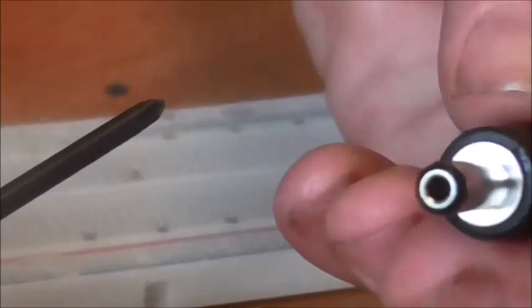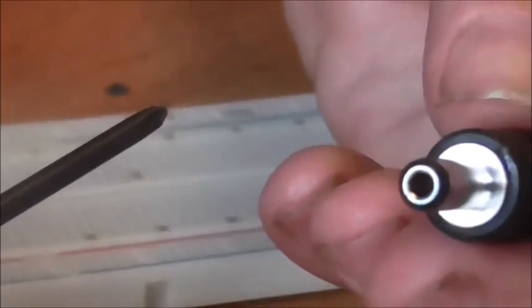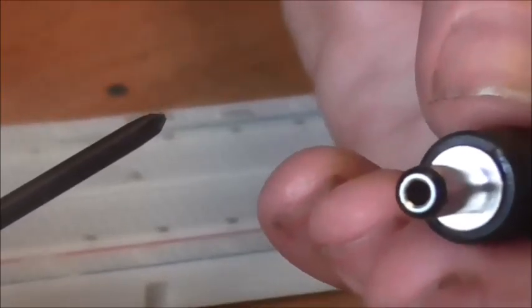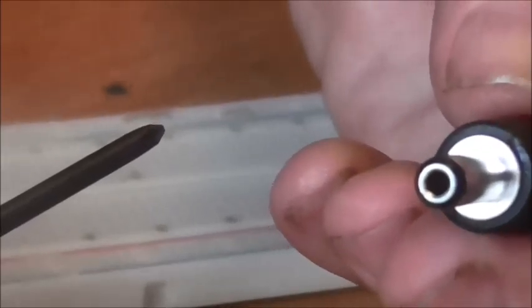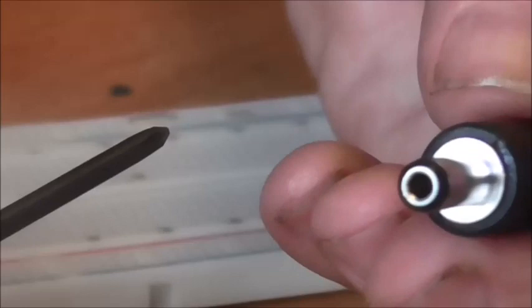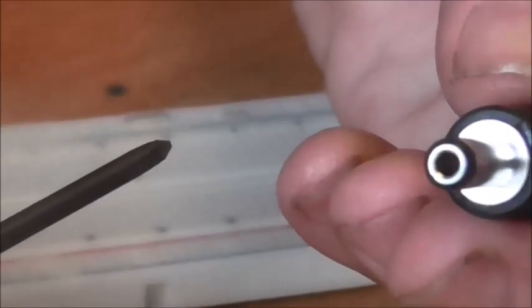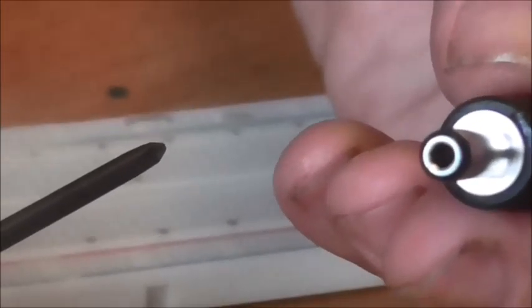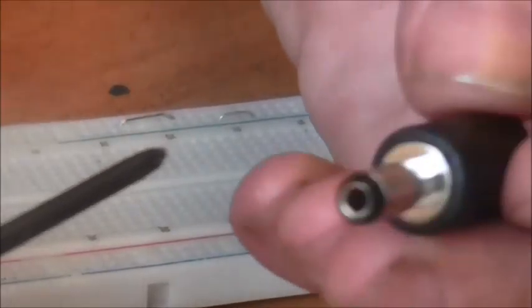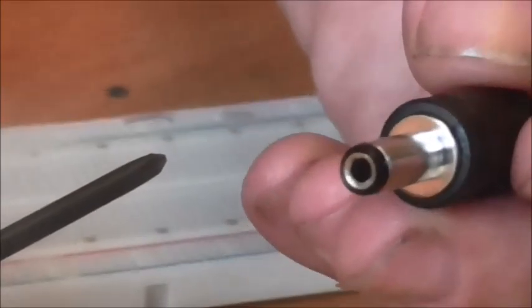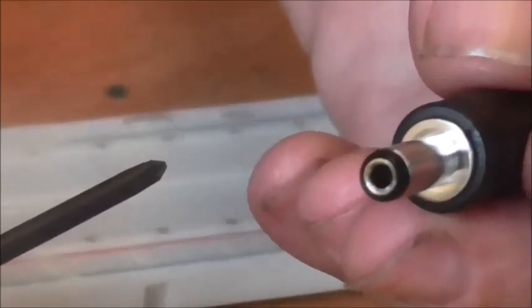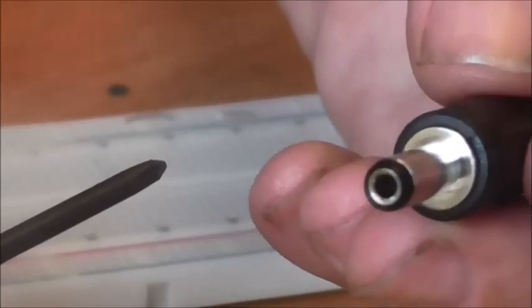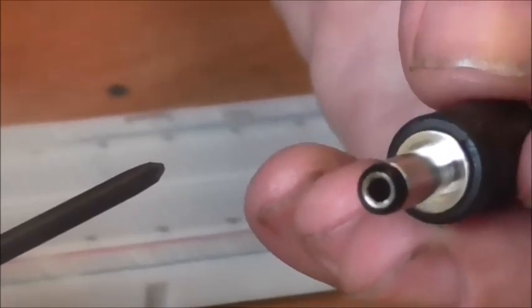What this means is that when you plug something in, you can give it the wrong polarity. The device may require centre positive, or it may require centre negative. Some chips will release magic smoke and blow up if you give them the wrong polarity. And so, in many devices, you will find a diode to prevent reverse polarity.